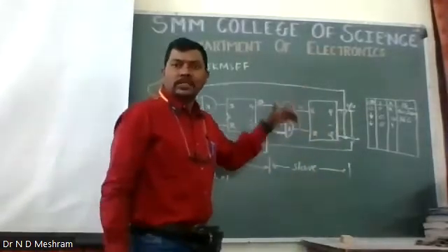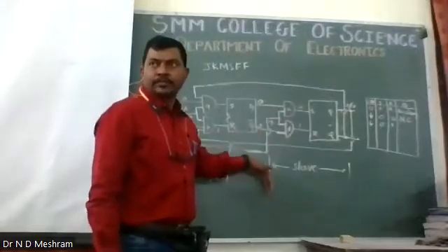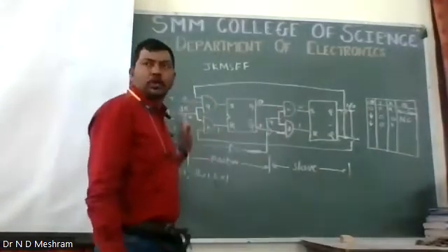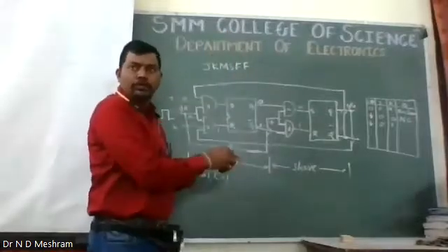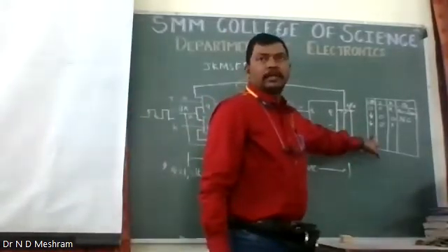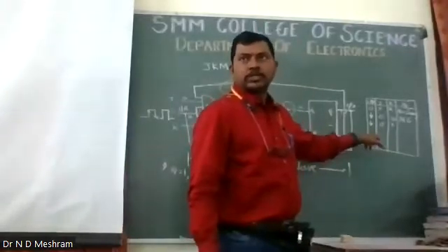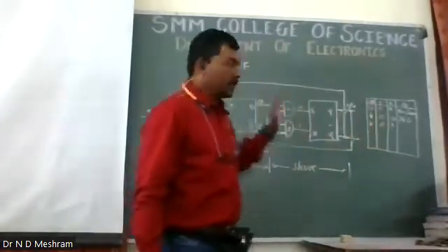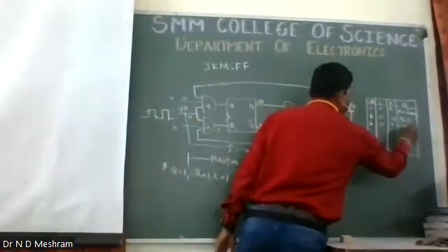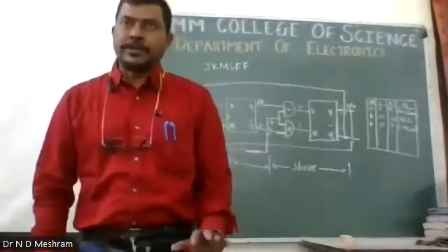So as you can see over here, this flip-flop is going to work on the negative edge, right? Though the output of the first flip-flop is going to change on the positive edge, the total output of the flip-flop is going to change on the negative edge. Therefore, I am writing here the down arrow, right? Because it is going to work on the negative edge. So the first flip-flop is now going to 0, that is reset. The output Q is going to change as reset.